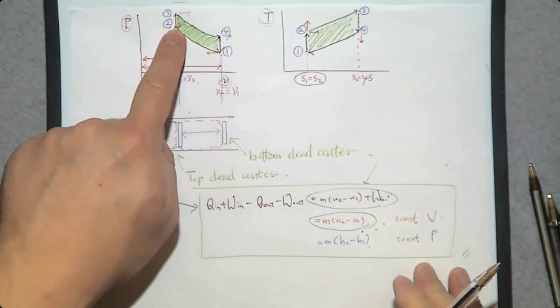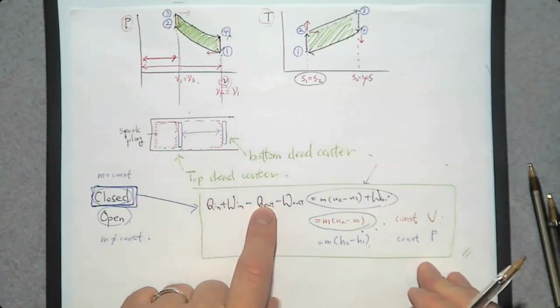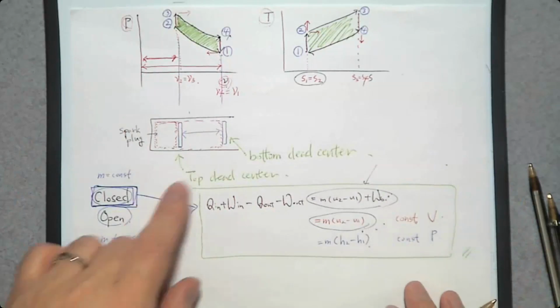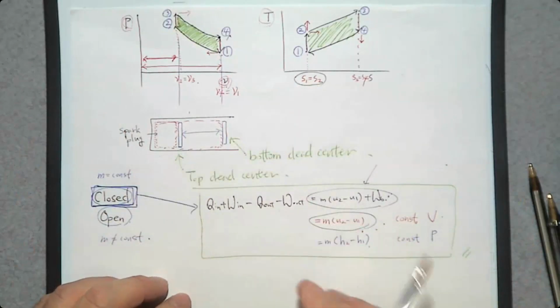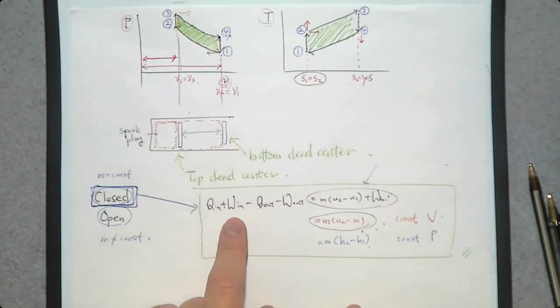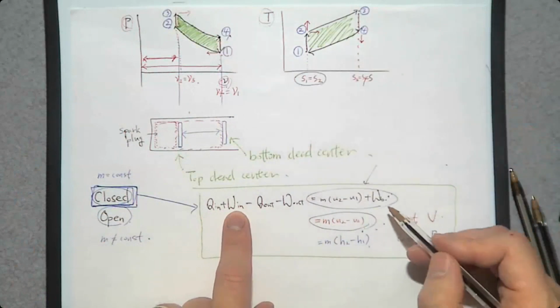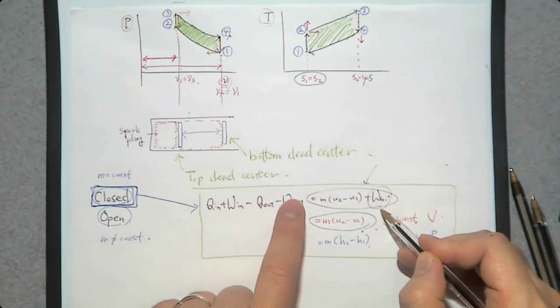When we have an isentropic compression process, we can neglect Q in or Q out, because when there is heat transfer, entropy should change. However, entropy remains constant, so we can neglect Q in and Q out. What about any external work? We have compression work, but the compression work is going to be here. So W in and W out, you can neglect them too.